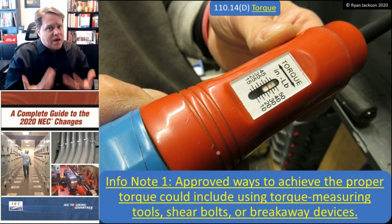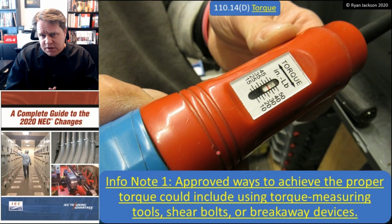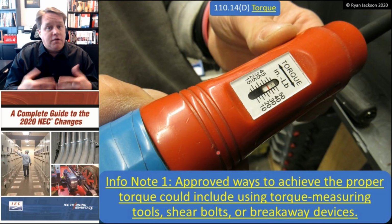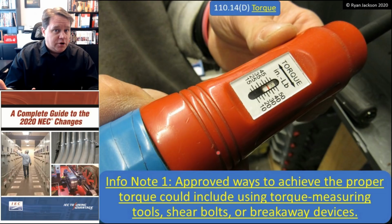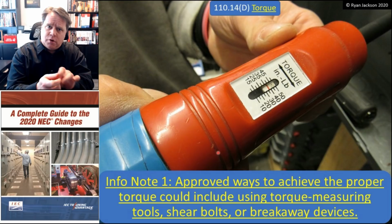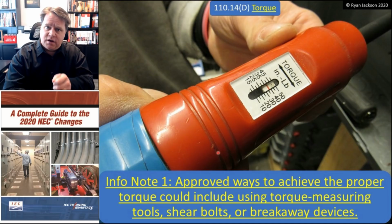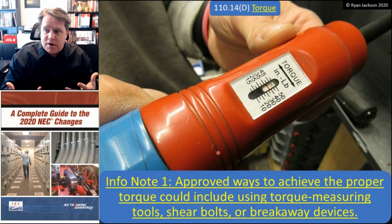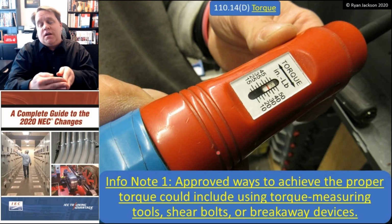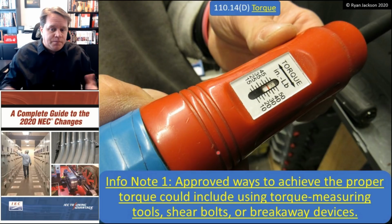Now, do they have such connections in the electrical industry? I'm led to believe that they do. There are some manufacturers of switchgear or motor control centers where the horizontal bus, where you might have to bolt the busing together, might employ shear bolts like that, where the end of it snaps off when you've tightened it correctly. And we can all agree that tightening our bus bars together appropriately is critically important.